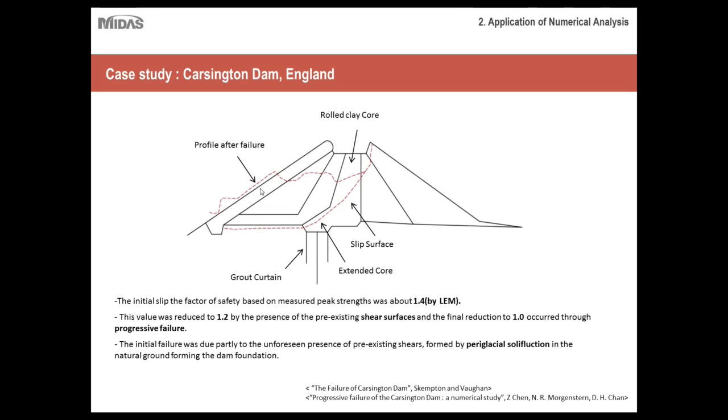If you can imagine the water level was around here for this dam, just imagine the water being frozen at one point. And as we all know, when water freezes, it expands. So when that water in the soil expanded, it caused additional shear. And then ultimately it melted, causing additional shear. Now this happened over the course of, I believe, several months. So over time, the shear stress became too much for the slope, and it led to its failure.